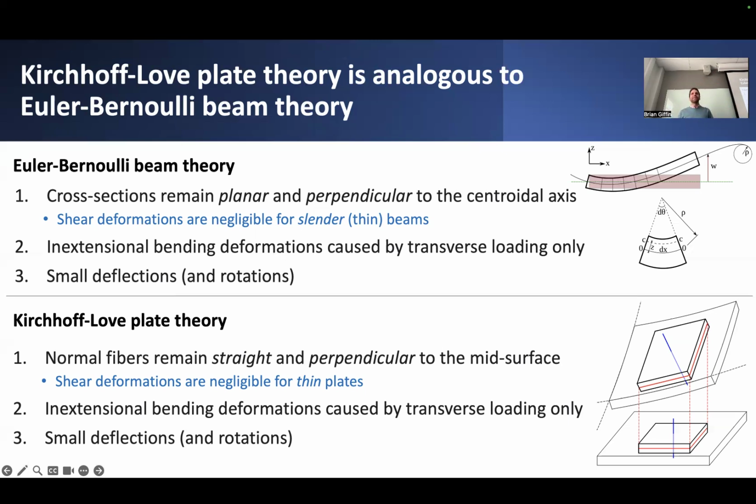Under the assumptions of plate theory, and in particular Kirchhoff-Love plate theory, this fiber will deform in a fashion which basically means if it was originally straight, it will remain straight after deformation, and it will also maintain an orientation which is perpendicular to the mid-surface of this plate.